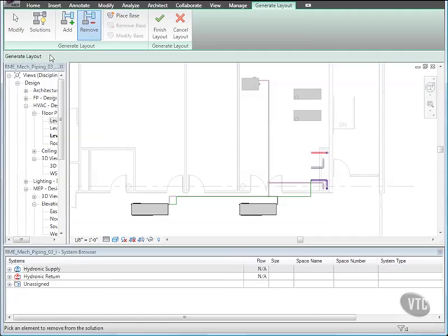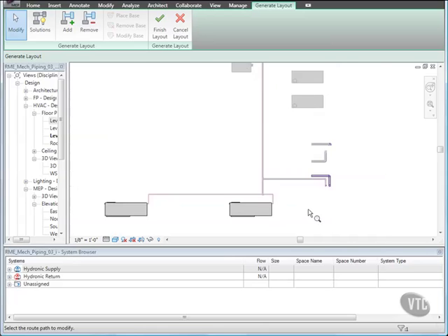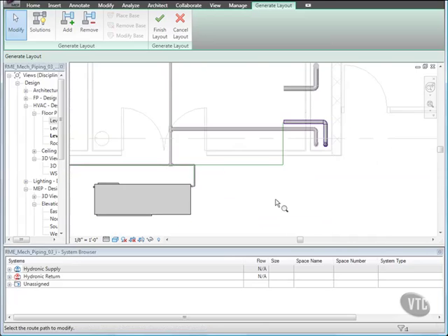Click Modify and zoom in and select the right vertical green sketch line as shown. Then, while holding Control, select the vertical sketch line just above it. Then, click and drag the 4-way arrow control to the left, just to the right of the double door in the underlay.